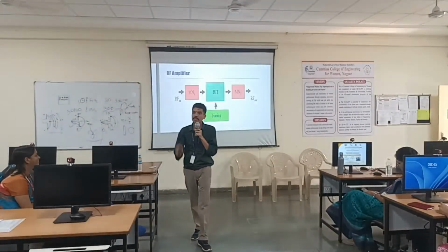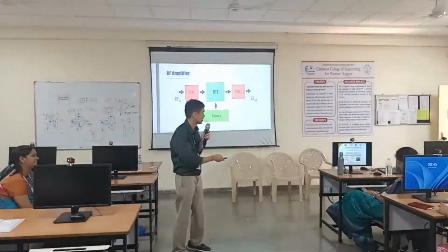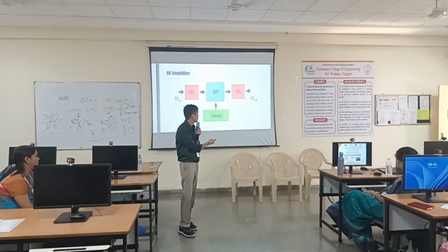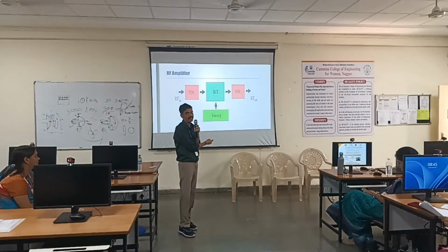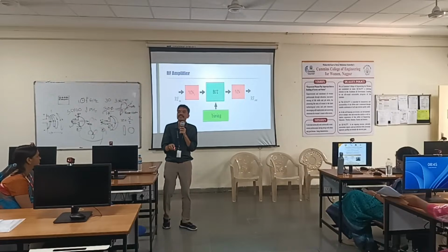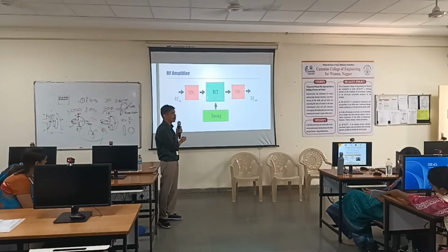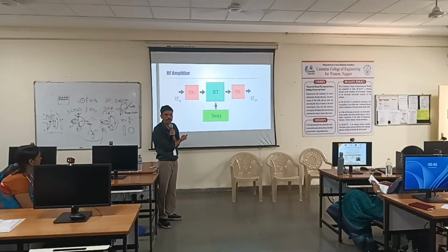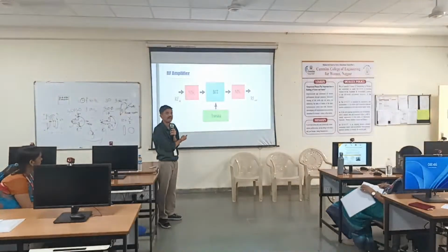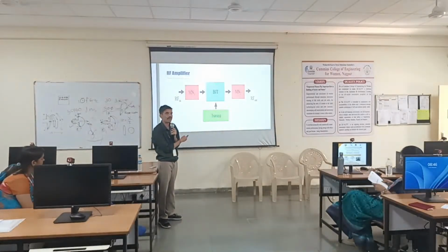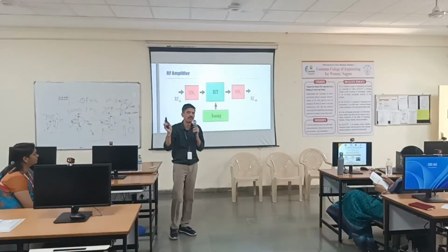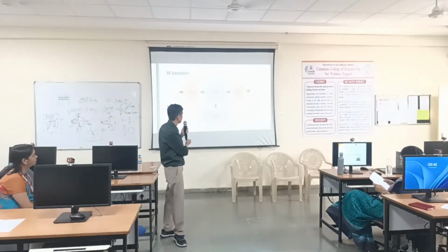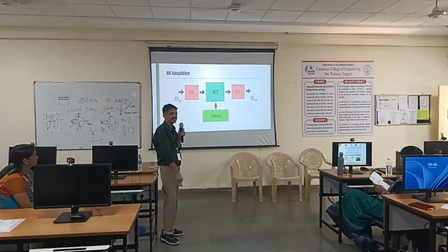Sorry. So impedance can be real, because just now I said no. This 50 ohm is what? A real number. Here also it will be a real number. But the story in between is complex. And what do we do? Here it will be R plus or minus jX. Similarly, the output impedance of the transistor will be R plus or minus jX. So now, to make it as simple as possible, how can you match a complex impedance with a real impedance?